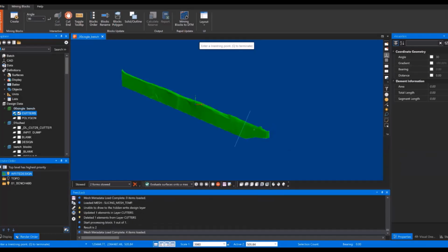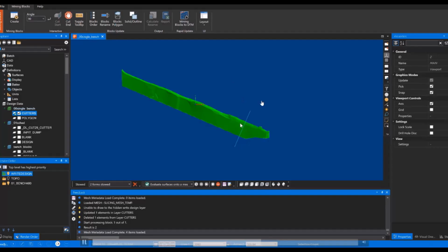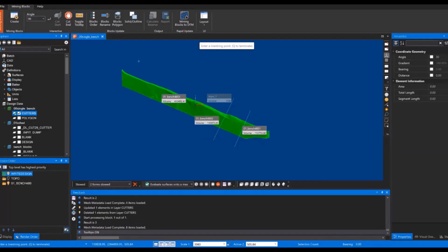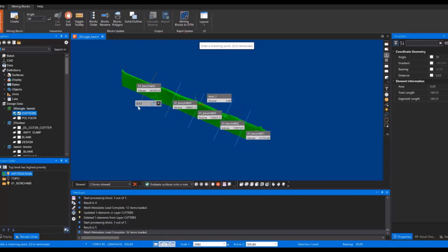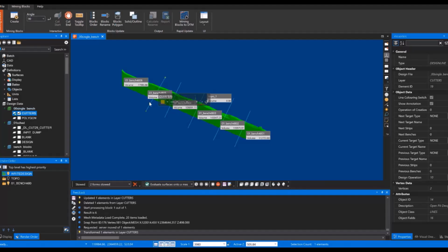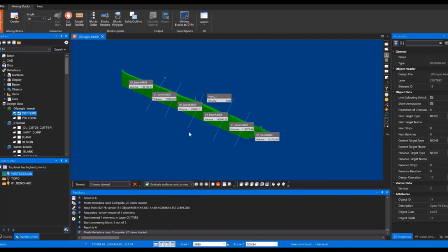And then when I do that, it automatically cuts. And for us to see that, I'll just toggle the tooltip shortly, just so you can see that it's actually cutting across. So toggle the tooltip, cut the second one first, and okay, toggle the tooltip, and you can see it shows you the different volume as you keep on cutting. So it's interactively as you keep on slicing, it shows you the volume that you currently have. So keep on slicing it through, and you can see different volumes in there that you have, and you can either delete the line or move it, and it will update as you keep on moving, showing you the volume.